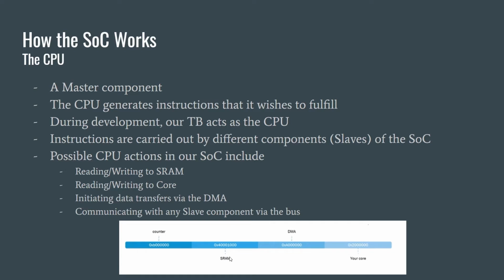Instructions are carried out by the different components of the SoC. Some possible CPU actions in our SoC include reading and writing to SRAM, reading and writing to core, initiating data transfers via the DMA, and communicating with basically any slave component using the bus.